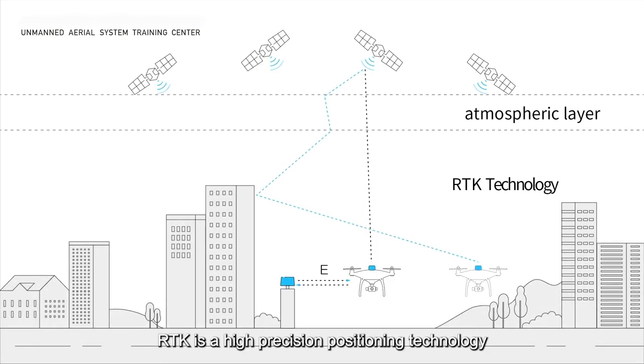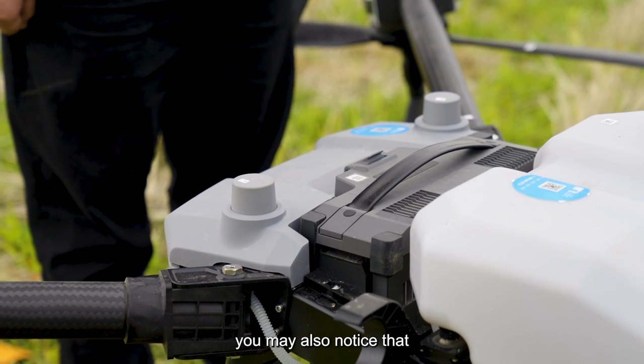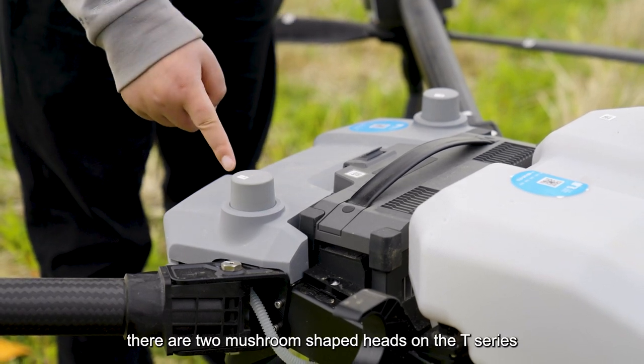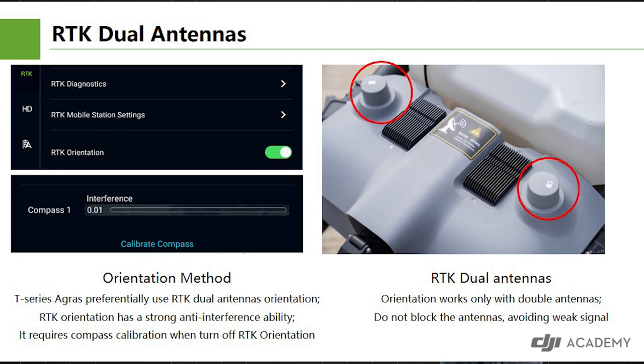RTK is a high-precision positioning technology, and the error accuracy can reach centimeter level. You may also notice that there are two mushroom-shaped heads on the T-Series agricultural drones, which are RTK antennas. The two RTK antennas can achieve a directional function, which is somewhat similar to the compass, to improve the flight accuracy of the drone and the ability to resist electromagnetic interference. If there is no RTK orientation function, the drone can only be oriented by the compass. So, if the RTK orientation is turned off, be sure to calibrate the compass.